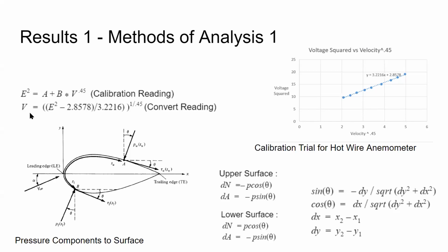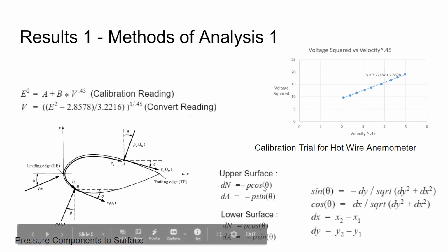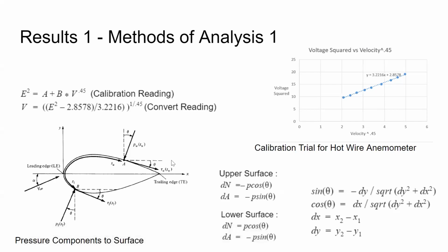The airflow, not airfoil. The second part, quantitatively, is calculations of lift from the pressure ports. So you can see here, the pressure will be acting downwards on the upper surface. So you see cosine theta will always be negative, and always positive on the upper and lower surfaces. The cosine theta is chord relative; it'll be the chord to the surface profile angle.